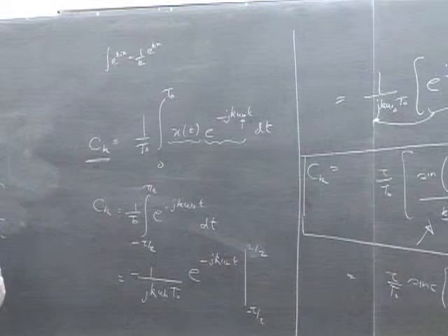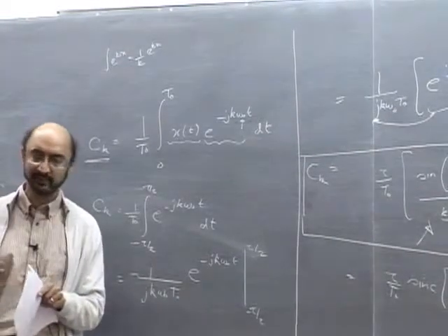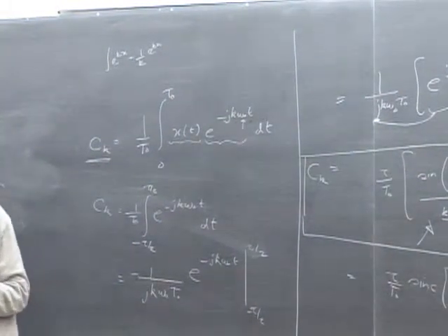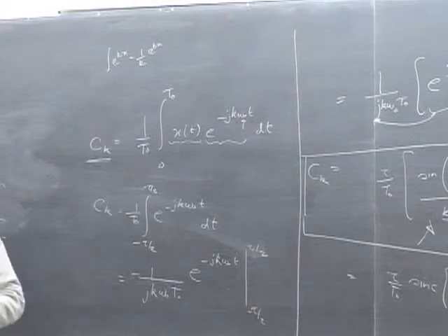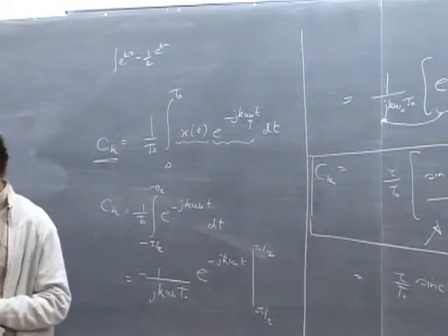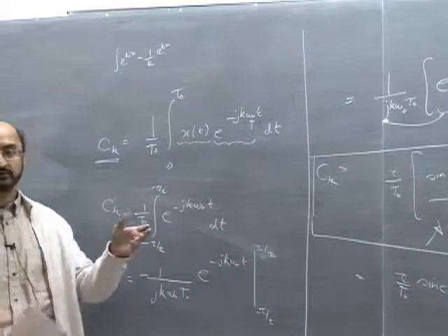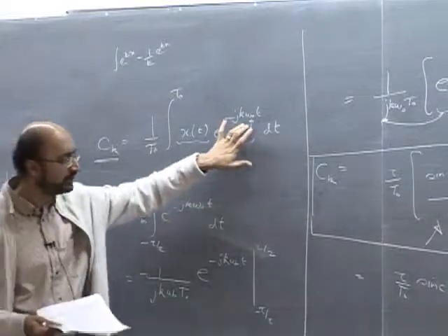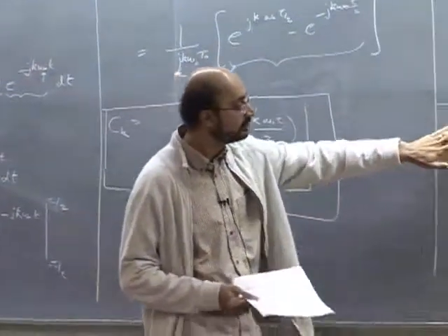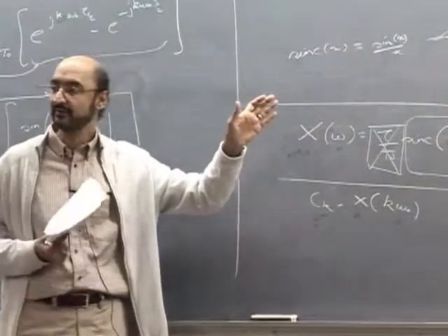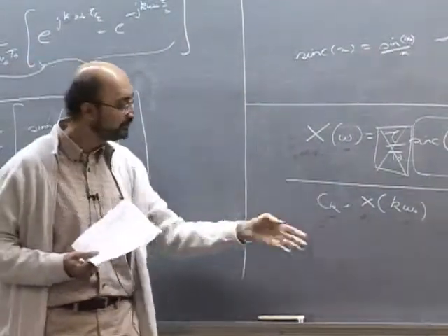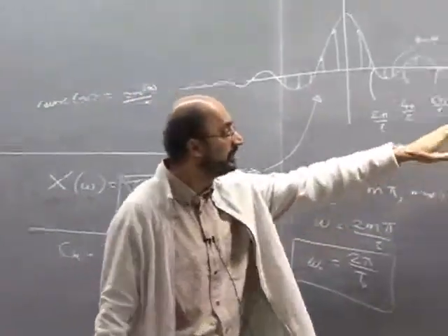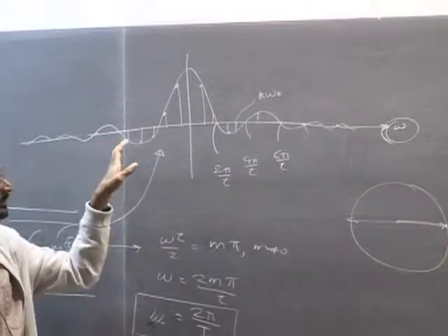So if you have a signal that's of period 1 second, then it's basically 1 hertz or 2 pi radians per second. And so we know that to express this, we're going to use harmonics of the frequency: 2 pi radians per second, 4 pi radians per second, 6 pi radians per second, and so on, right? That's what Fourier series tells us. So from that omega naught, which has a very natural physical meaning, we came to the use of X of omega, where now omega is the generalized angular frequency, sampled at the points k omega naught. And from that, we come to omega as an axis, and this function over here, which is being sampled.